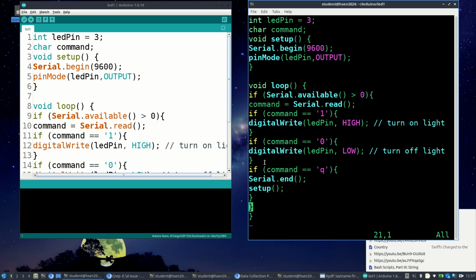So when you connect, what you're going to want to do is connect your resistor at pin D3. Okay, so you remember how to do that? You have to put it in one of the holes that's right beside D3. The other leg needs to go into a different row, because if you put it in the same row... I would actually put it out to the side, along the rail that's marked with red, right?